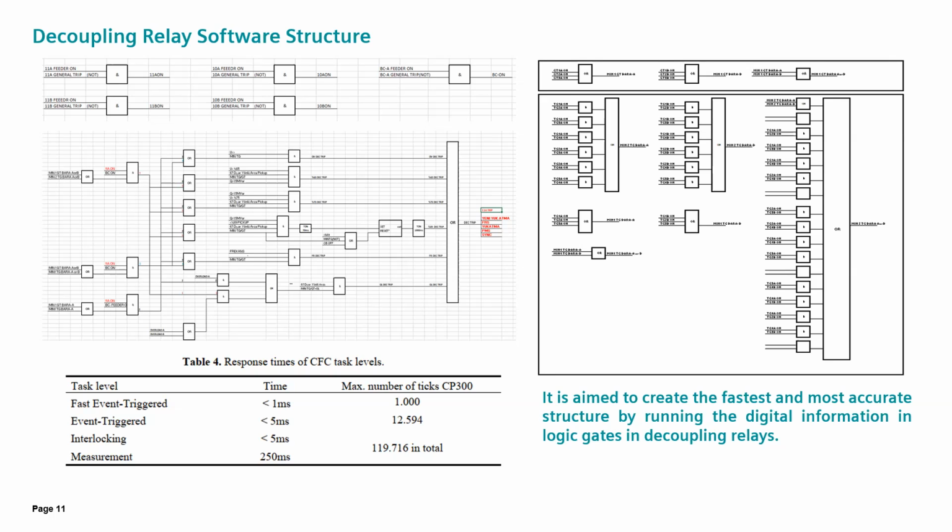Our adaptive decoupling system is designed to act automatically and to avoid any human mistake during critical operation in limited time. On the other hand, we have also designed our system and are creating additional development to reduce the operation time in our system. For example, the first item that you can see on top of the screen, the feeder-on signal and no-trip signal are connected to AND gate and logic gates. By doing so, we are eliminating the need to wait for the circuit breaker opening time.